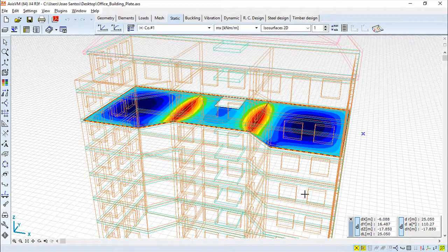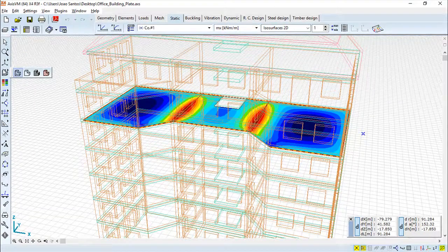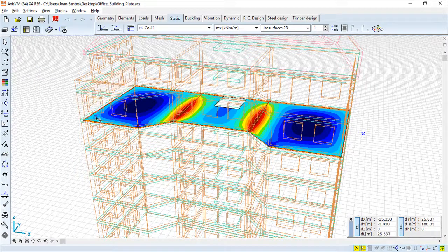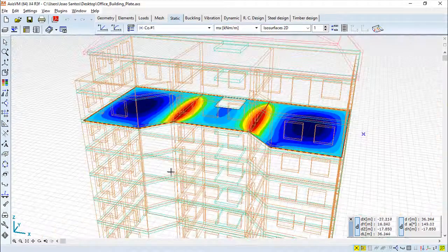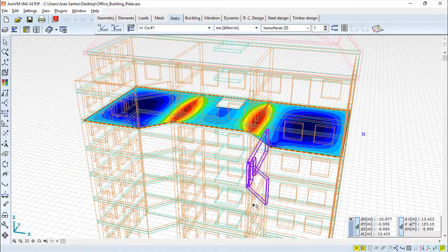Going to the next one, we go to something called the display mode. And the display mode allows us to display the model in different ways. The one that is called wireframes, which is what we have. We have another one called the hidden, that displays a wireframe model drawing with hidden lines removed. Then we have some parameters to set this display, okay.